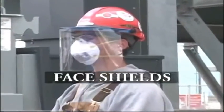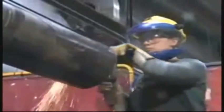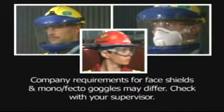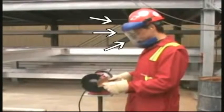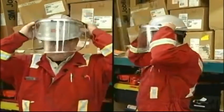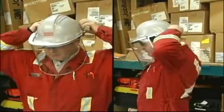When completing your hazard assessment, depending on the hazards involved, you may be required to wear a face shield in addition to your safety eyewear. Face shields provide extra protection from flying particles and sprays of hazardous liquids to the eyes, forehead, cheeks, nose, mouth, and chin, and where required, to the front of the neck. Ensure you attach and remove your face shield properly from your hard hat.